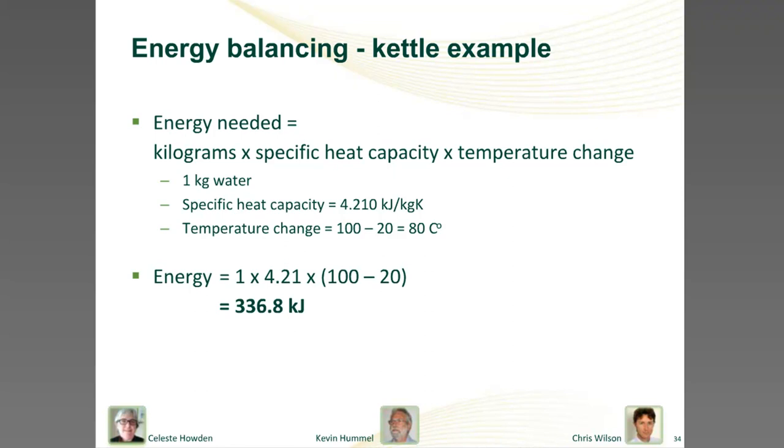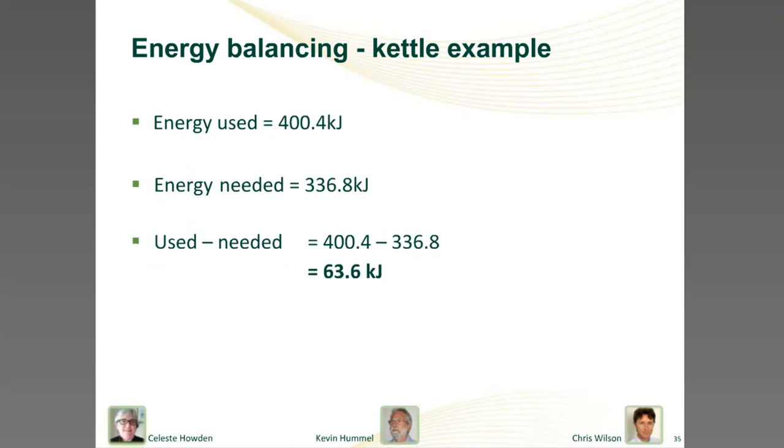The heat required to just heat the water and only the water with no waste. But we just calculated we have in fact used 400.4 kilojoules. So what happened to the remaining 63.6 kilojoules? Well, clearly this is a waste, and it's almost 16% of the energy we've used.